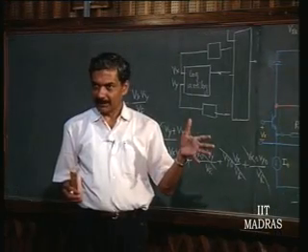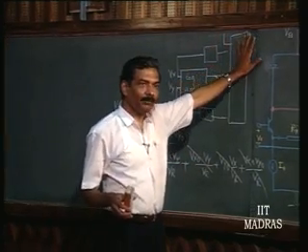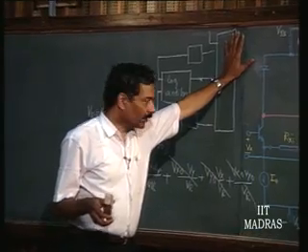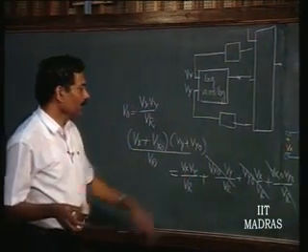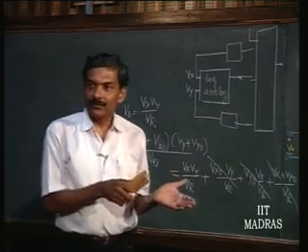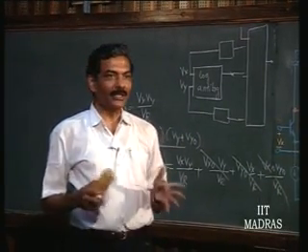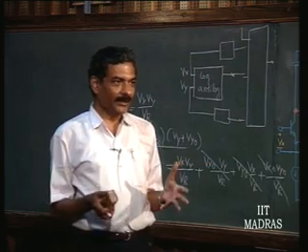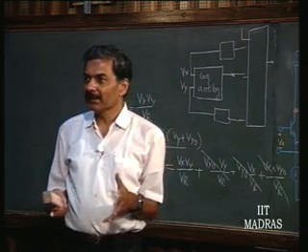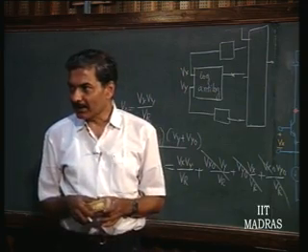Please carry out this simple exercise using a simple op amp adder or subtractor. You can obtain this kind of conversion from single quadrant to 4 quadrant. That is very simple. That is why nobody bothers whether the initial precision multiplication is achieved using transistors in such a manner that you have only single quadrant operation.